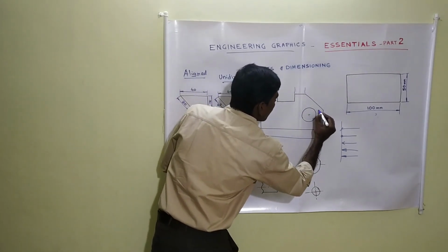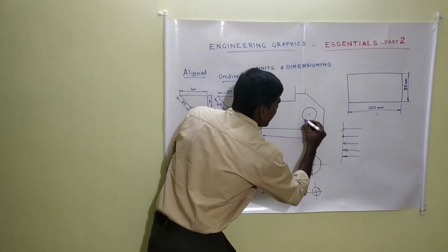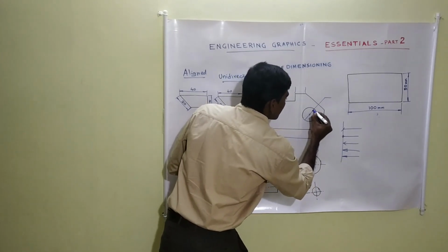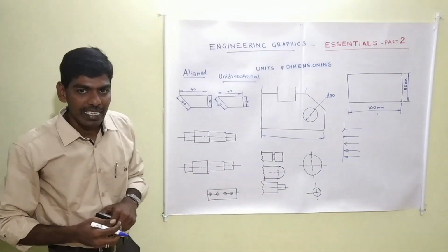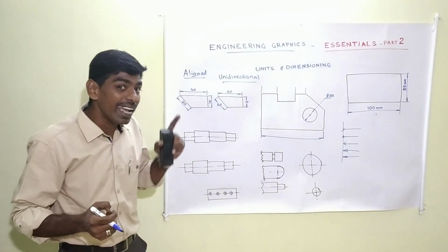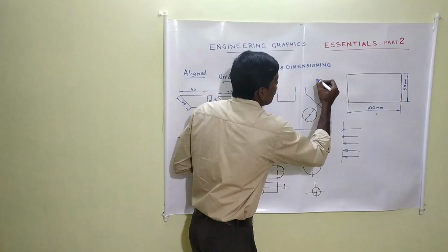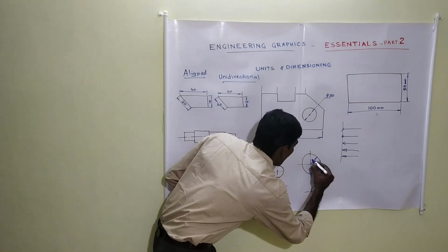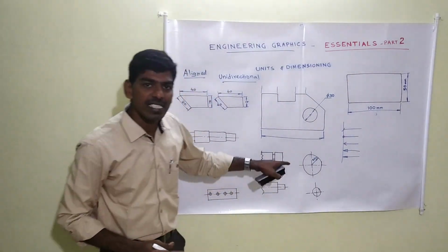Again, for example, if I want to give an angle here, I want to give angle. And again, here it's a center mark. I need to give this one. So I can use a diameter, say to be 30. This indicates diameter 30. For a circle, we need to give either diameter or radius. If I want to give radius, I should give it in another way. For example, I can give it this way. R 20. That means radius 20 for this circle.